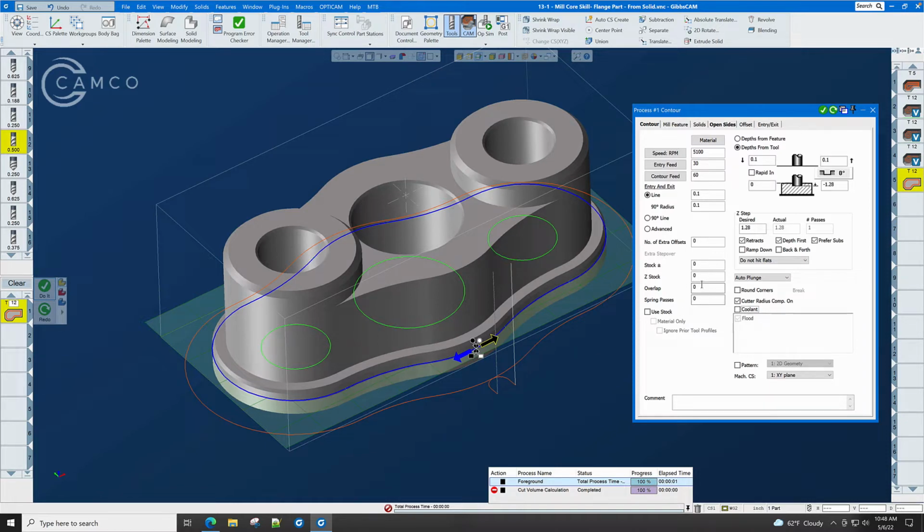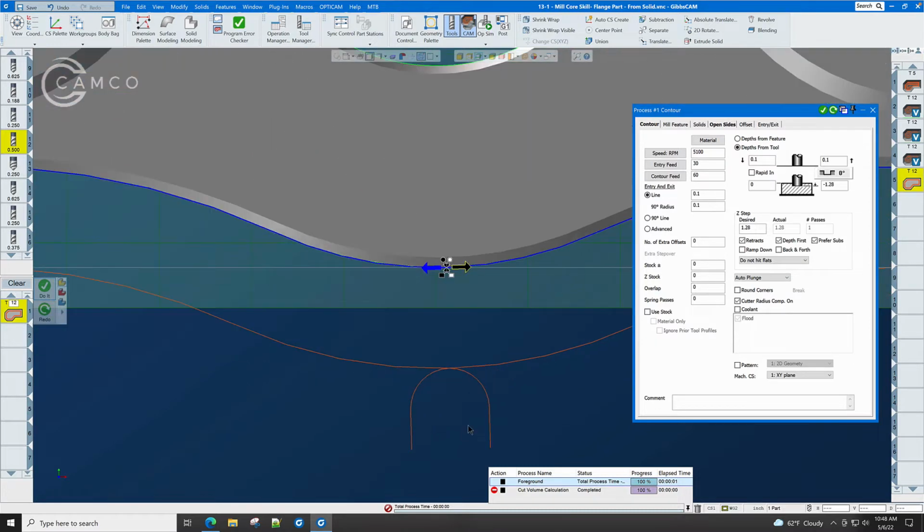We said we were going to go back and talk about overlap. Overlap simply means that when we have an entry line, which turns on cutter comp, and we have an entry arc so that we gradually and gently move into the part, and then we go all the way around the part, and we depart here where the 2 arcs meet. This is going to leave a little witness mark. We want to get rid of that witness mark by adding an overlap of, let's say, 50 thousandths.